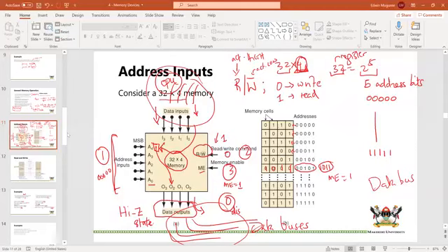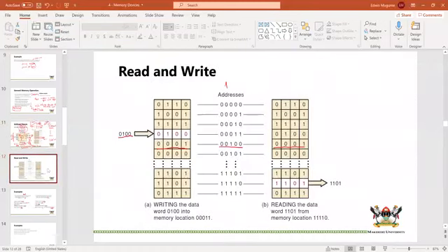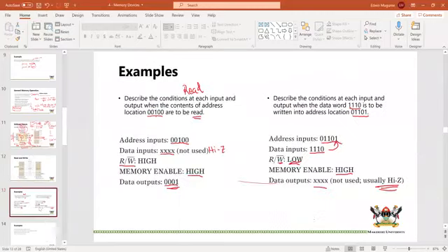We cannot both read and write simultaneously. So that means when we are reading, we can use the data lines. And when we are writing, we are not reading, and so we can still use the same data lines. Obviously, that is why, if we are using the inputs, we put outputs in high Z so that there is no collision on the line, on the bus. Okay.